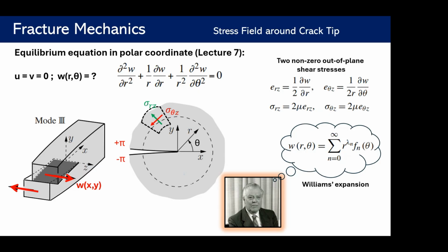Anyway, by solving the equation, we have just one unknown here, W. By solving just one equation, we can find the out-of-plane displacement field. Based on the displacement field, we can also find the out-of-plane shear stresses. In third mode, we just have two non-zero shear stresses, and those are out-of-plane shears.